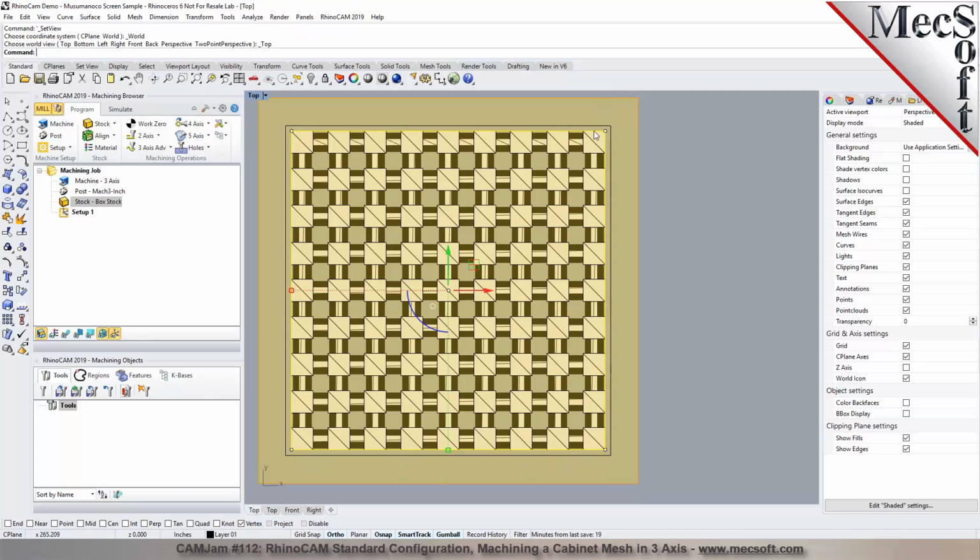Cool. Now, that 3/8 inch offset is just assuming that you're going to rough it out, say with a 1/2 inch bit. This offset needs to be wide enough just so your cutter can get in there. If you're going to use a larger cutter for roughing, you want to have the offset distance at least the diameter of the cutter, right? Right. So for practical purposes, I just made it 3/8 of an inch for now.